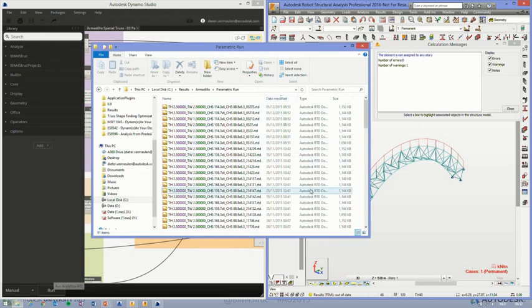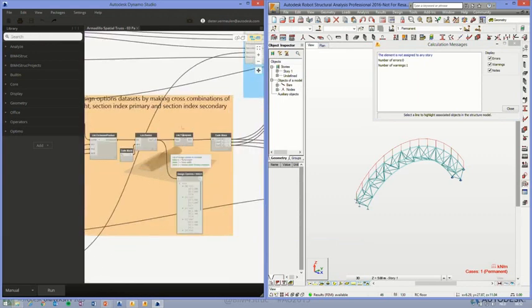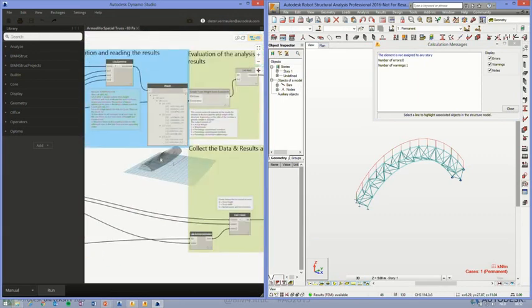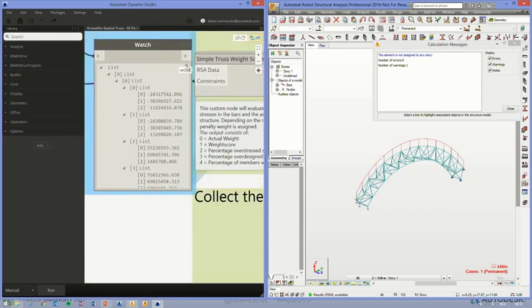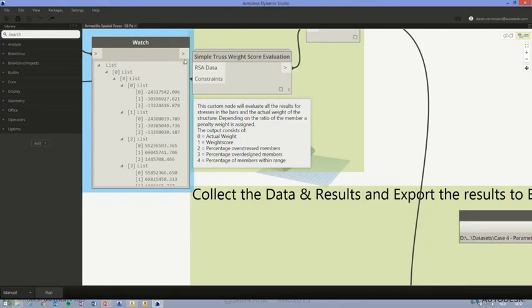It's, well, it's combining lists. It's a specific list handling method in Dynamo. If you have a function, so this is my function, my routine is generate structure, generate results, give me back those results. That's the function in here. And list combine will use that function as some kind of combinator and take the design option values, bring them into that function and perform an automatic analysis, some kind of iteration.